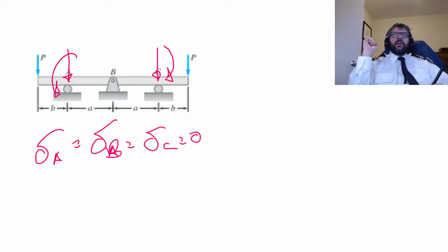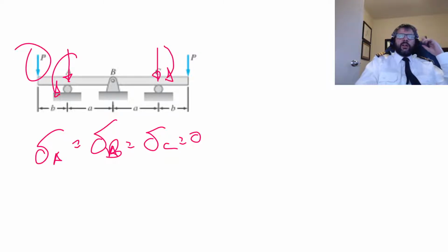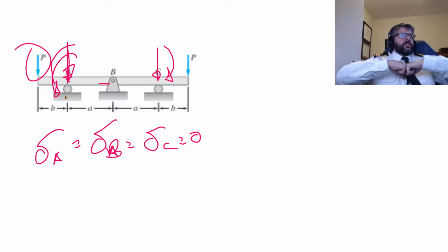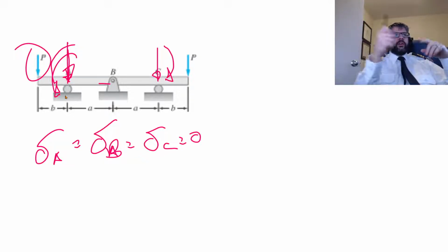And if we did that, then between A and C, that's going to cause the same displacement shape as if we applied P. Just that moment will do it, because the force itself applied at A, if you're pushing straight on the pin, just pushes back. But that moment there is what's going to cause your displacement in the middle.